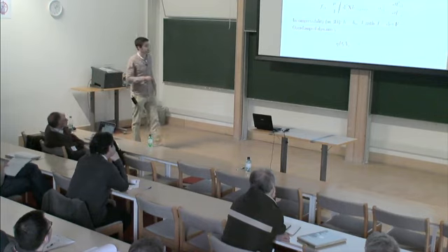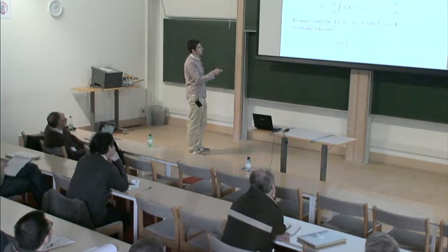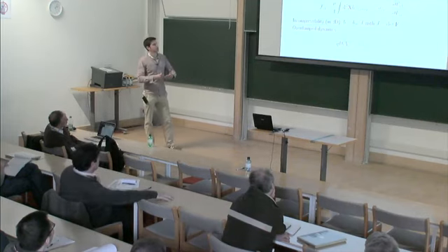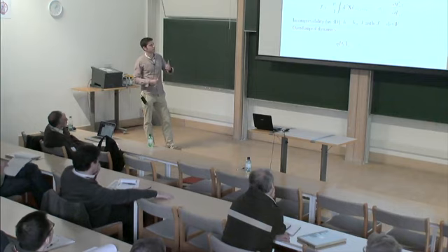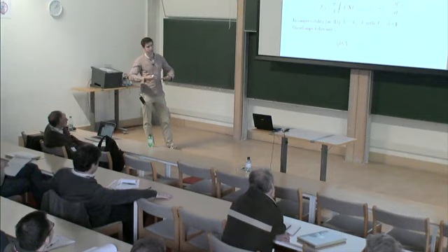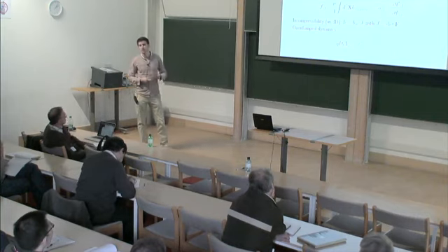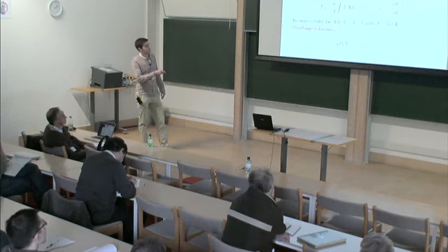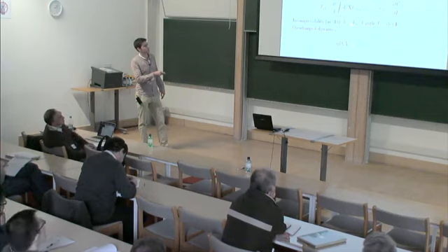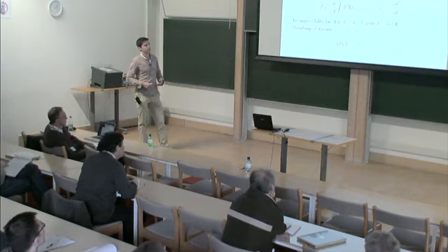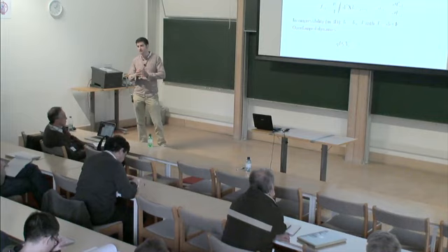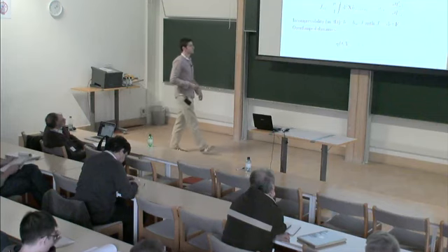Yes. So, as I said, we are essentially two-dimensional, but then we need, of course, to have some relation between the thickness of the layer and the two-dimensional dynamics. We make here a simple assumption that the material is in 3 dimensions incompressible, which means that the height is given by the initial height over the Jacobian of the in-plane deformation, which basically means if we compress the layer locally, it becomes thicker. If we stretch it out, it becomes thinner locally.